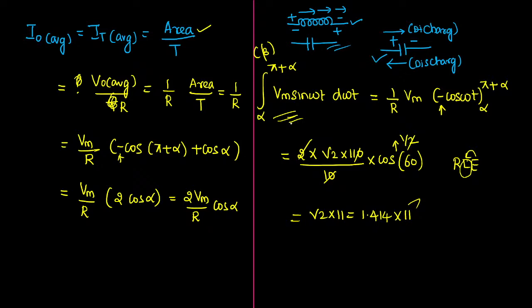Okay, so at the end, in steady state, the inductor will be short circuited, so what is the point of considering that effect while calculating the current? It is there, energy is there, current flow is there, but the inductor will be behaving as a short circuited one. Distortion effect will be there. We are not supplying a pure DC waveform here, I know that, but we are assuming that the effect has reached steady state, and we are not considering that effect.